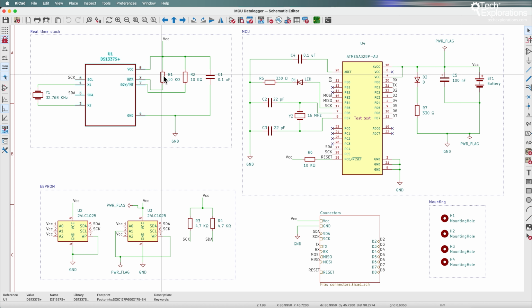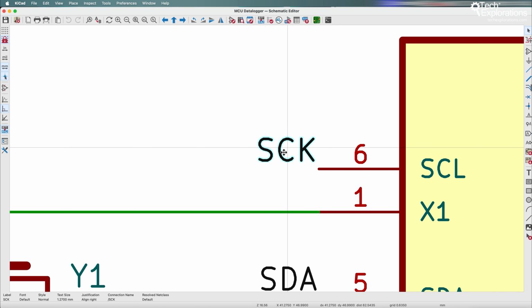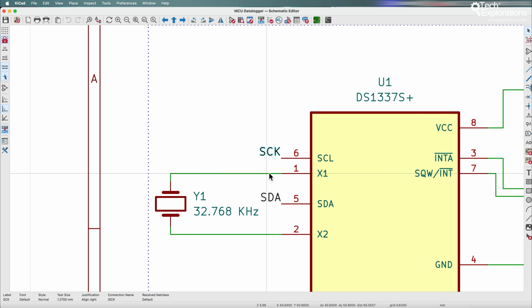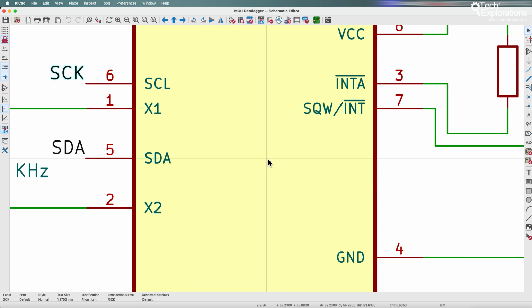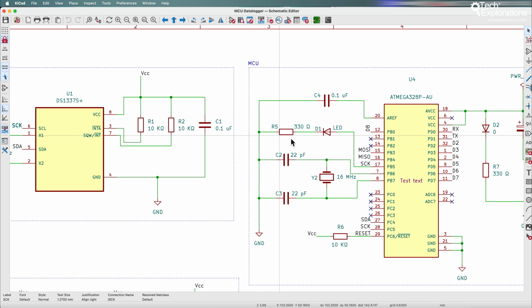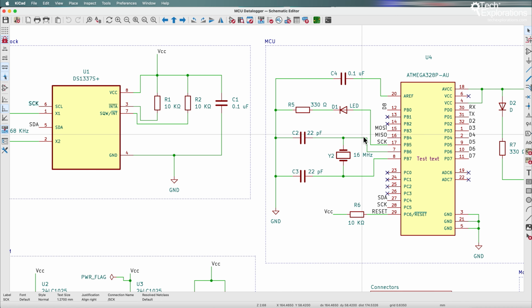There are components, such as these resistors or this integrated circuit symbol. There are also wires, and the wires can look like actual green wires in this case, or we can also use names, such as this label here, which is an alternative way to connect pins together. Instead of using a wire, we use names. So whenever you have pins that are connected to the same name, such as SCK here and SCK here, these are actually logically and electrically connected to each other.